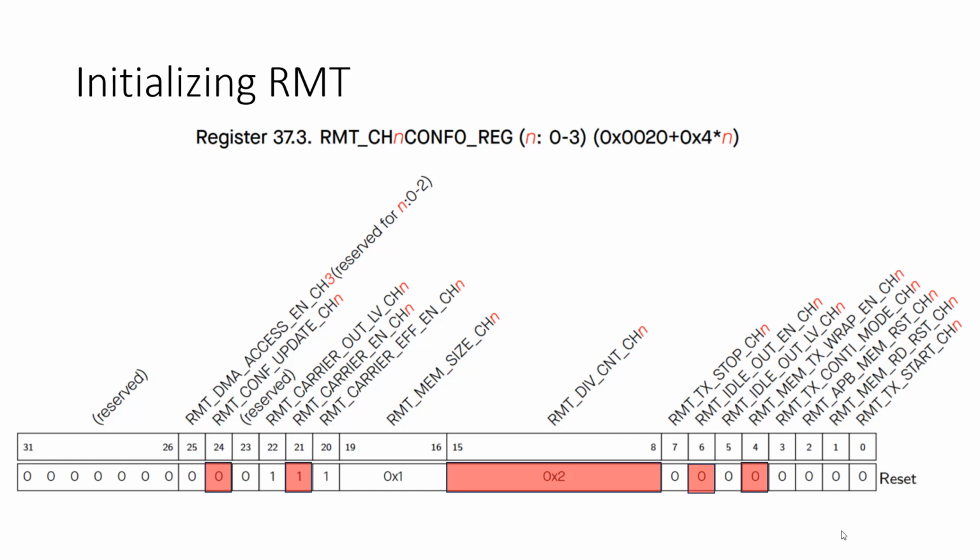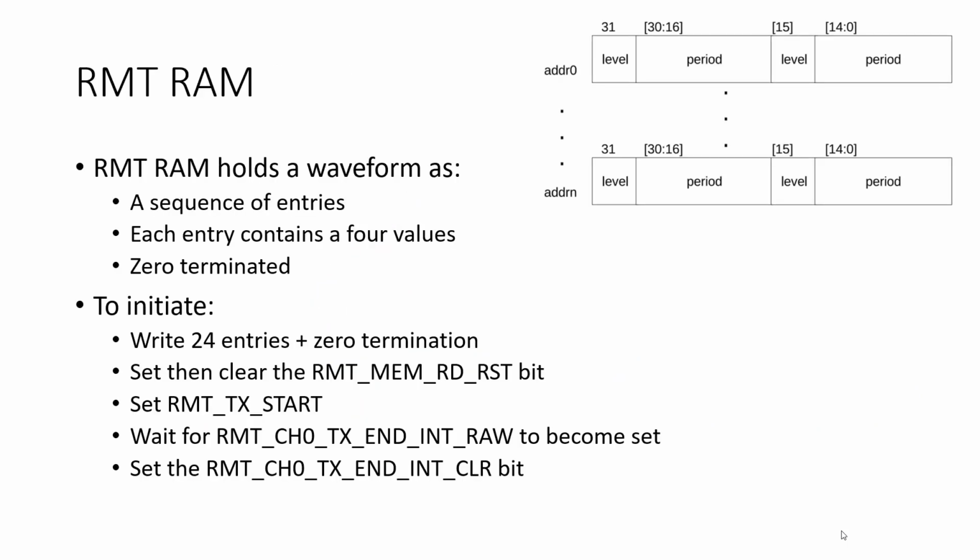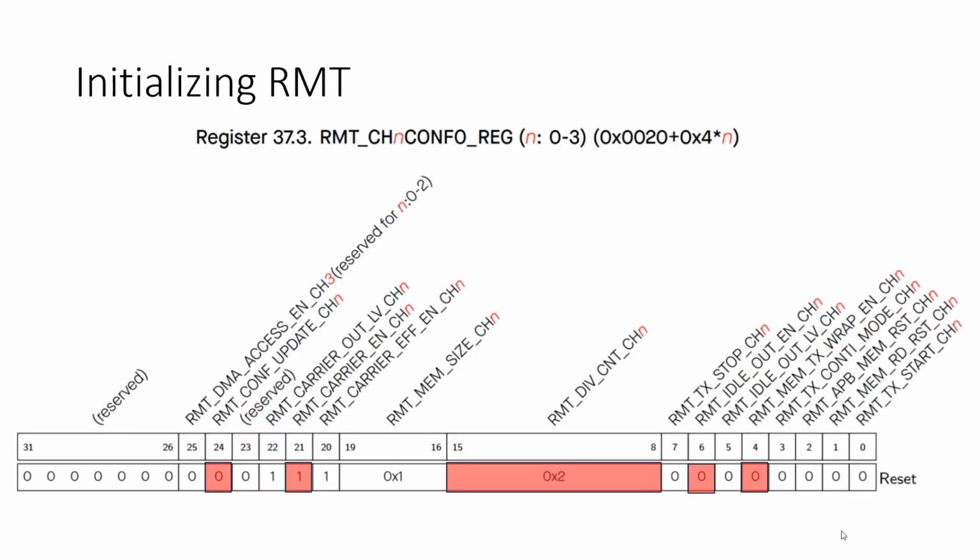Alrighty. So that's register number 2. Okay, so the way the RMT works is that was basically for setting things up. Now, by the way, I'll mention this, hopefully I don't make things even more confusing. There is a config 1 register for channels 4 to 7, but not for 0 to 3, as I learned recently. So there's no config 1. We used to have one last year.